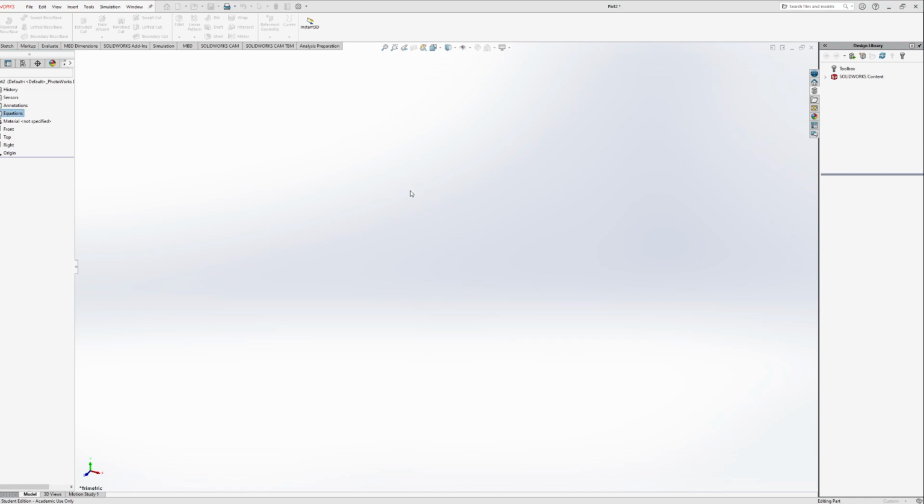So under global variables, there's a white box that says add global variables. So here, all I want to do is add each and every one of those variables that we've assigned, or the variables that were in that SolidWorks drawing. So our first variable a, I'll type a into the global variables box, and then I'll just hit enter. It'll direct me to that second column which says values and equations. And now we can actually do a whole bunch of stuff.